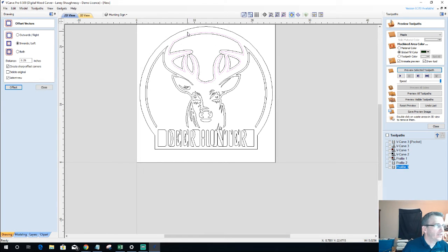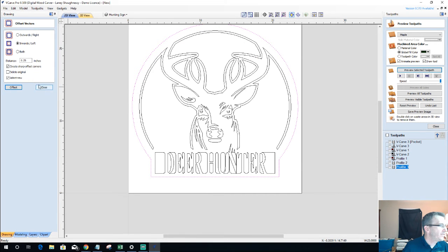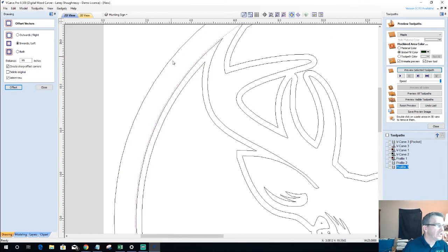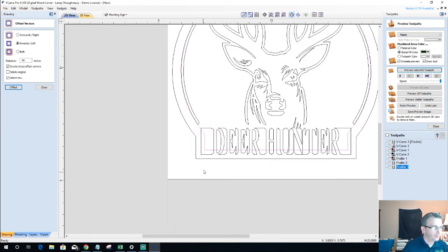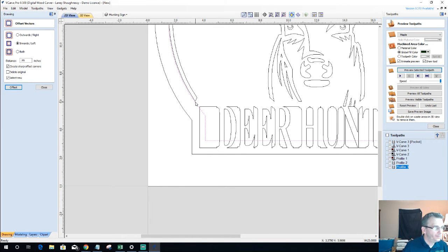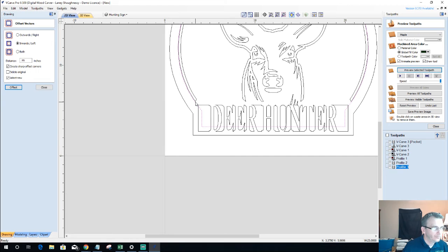Alright, so if I V-carve, it cuts between the lines. So it'll V-carve that. I don't want that. I want to skip. Skip to Lou, my darling. I'm going to offset that circle inward. It was 1 inch before. I'm going to go 0.95, offset inward, just to keep me about 10 thousandths off that, and that'll create this outer boundary.